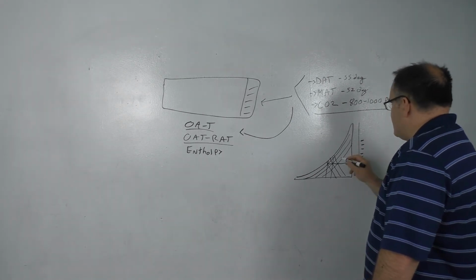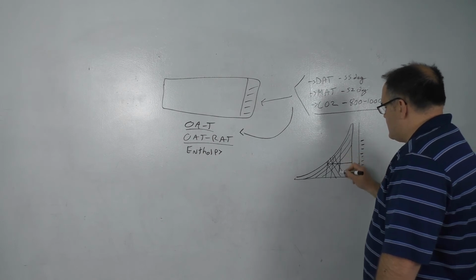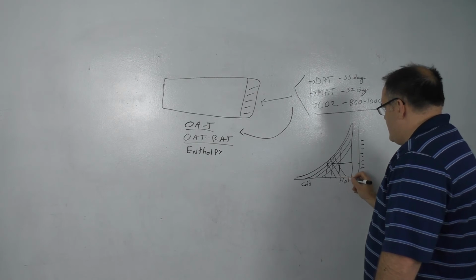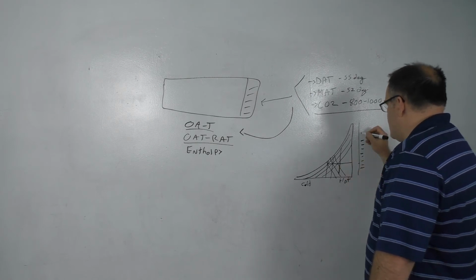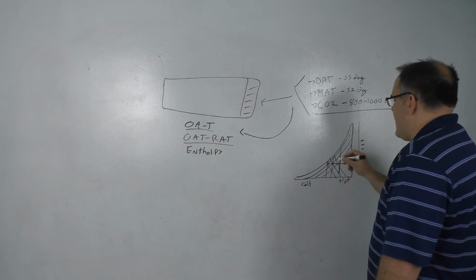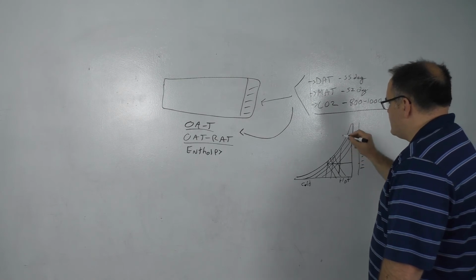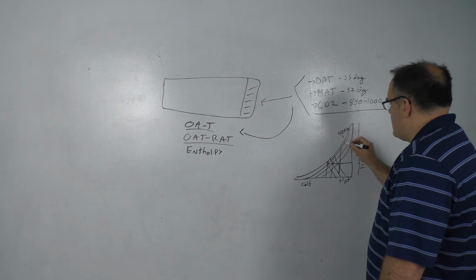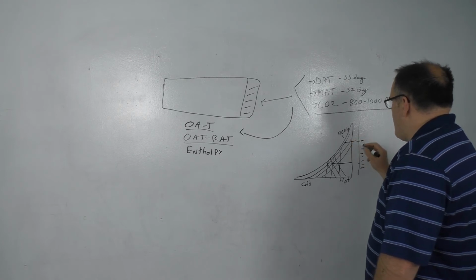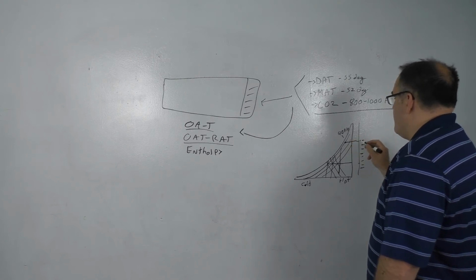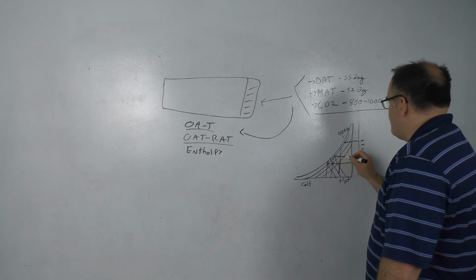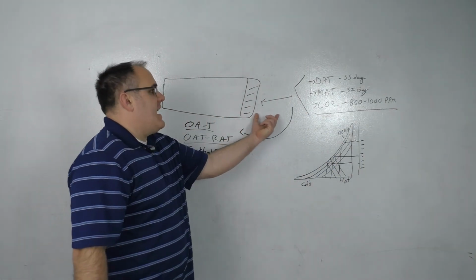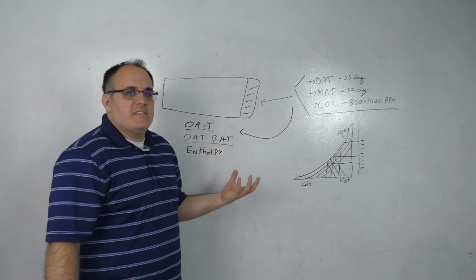And what happens is at warmer temperatures, so this is like cold and this is hot. So at warmer temperatures, you have more moisture in the air at the same relative humidity. So if this is like 90% RH, then here at 90% RH, you have a lot more humidity or moisture in the air than down here. Well, enthalpy control looks at the amount of moisture in the air because moisture contains energy.